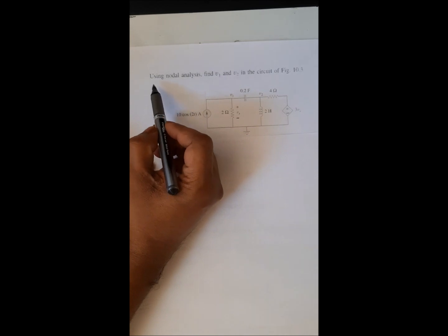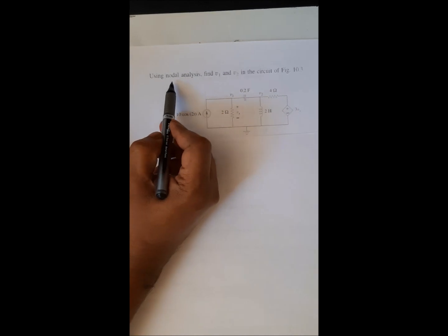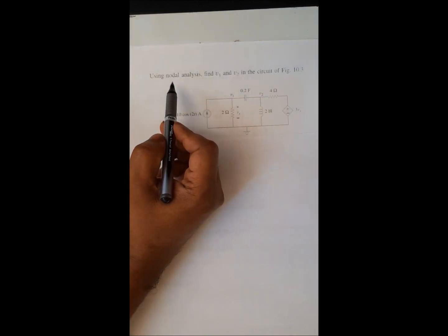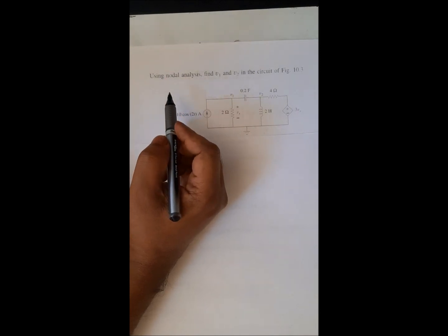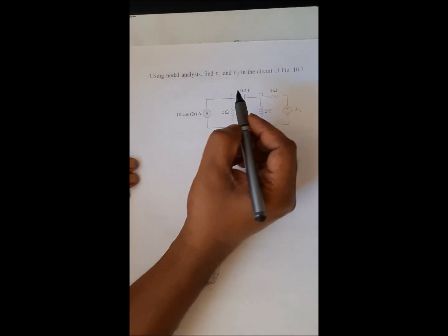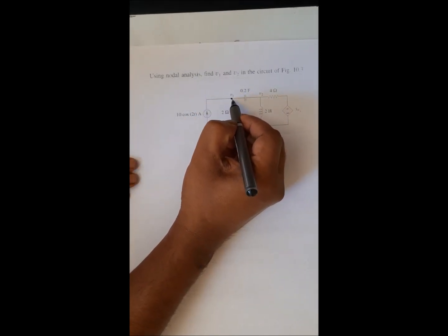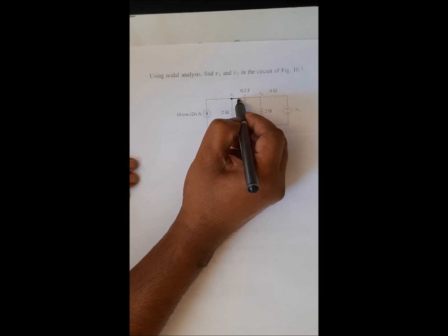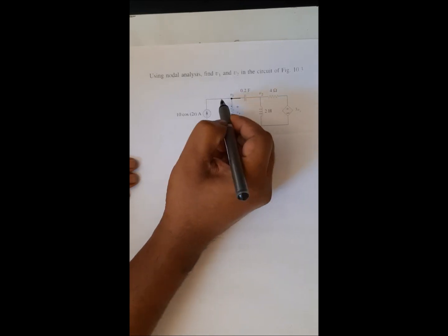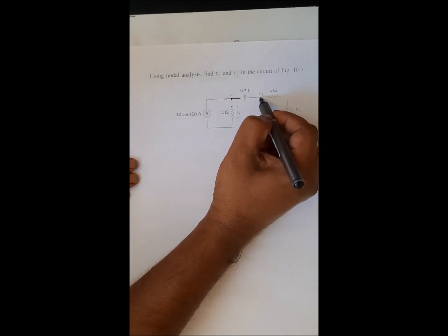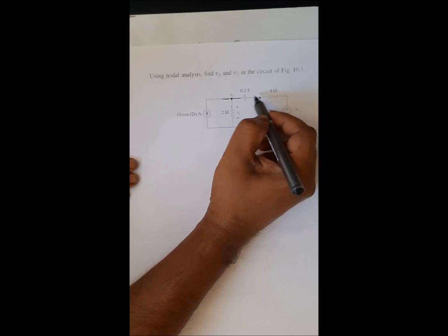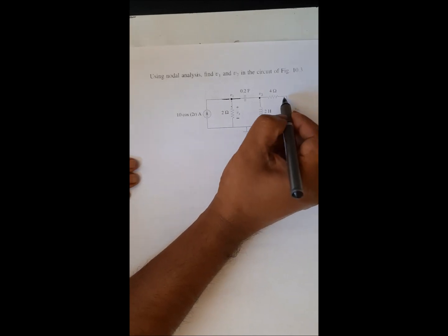Let us solve this circuit using the nodal analysis method, the node voltage method. In the node voltage method, as we discussed in DC circuits, we will be using the same concept for AC circuits. At first we need to identify the nodes. Here we see one node, because at this point a capacitor, this resistor and these inductors are connected. And we also see another node here, where an inductor, a resistor and a capacitor are connected.